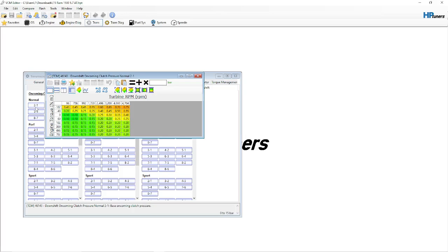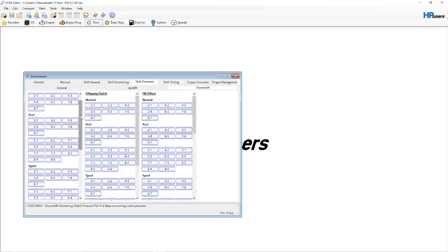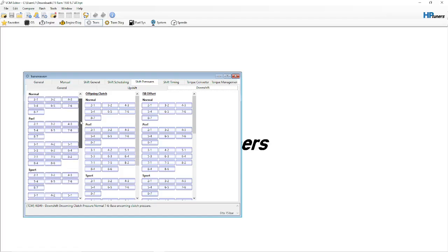this is shifting down from second to first. You have to be able to kind of decipher where these parameters sit. You'd have to go through your data log and see where these values are within your RPM and other correlations. But again, normal driving, you're driving your truck to work. Typically, you want it to have that performance. You want it to be able to shift efficiently and have good fuel economy. All that stuff's good. That's where we end up setting this normal at.